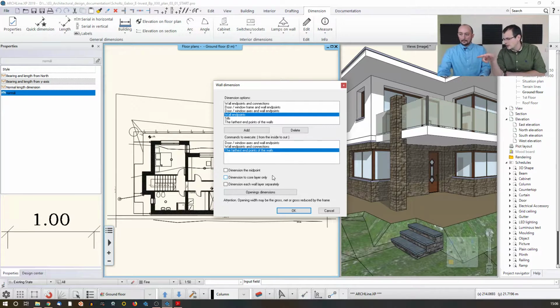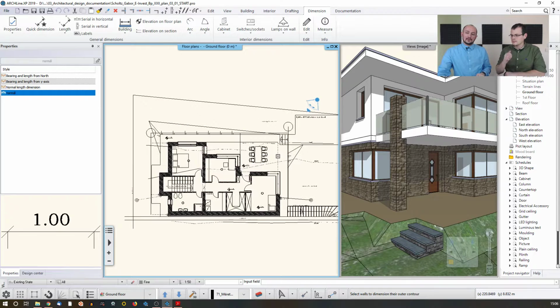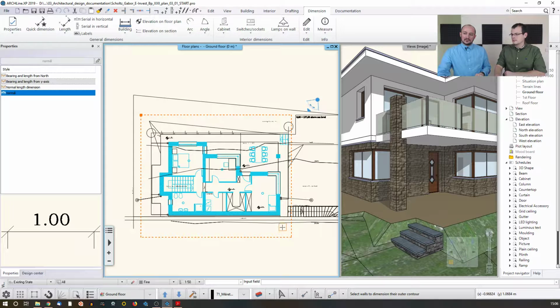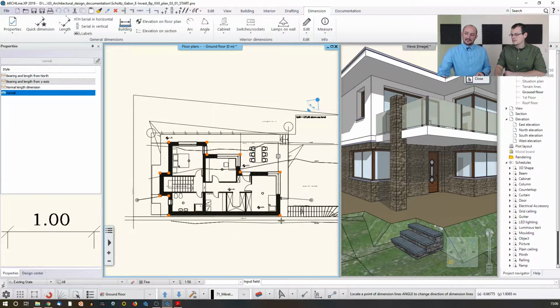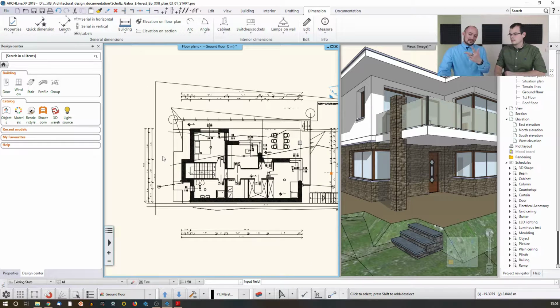So first you select the criteria. Now we have 3 listed, and then what do you do? Then what I do is click OK, and then I can select the whole building. This is one of the fastest tools, because whenever you have a complex detail, either this type or another type, you can just hit enter, set up where the dimension string will be, and then the software will create that dimension string. Actually, in this case, 3 different specific dimension strings.